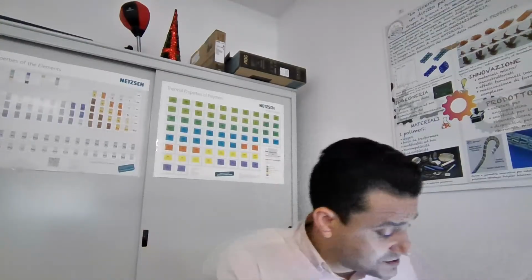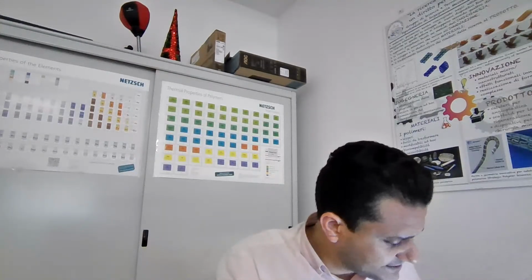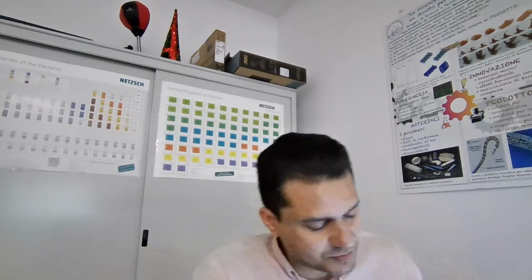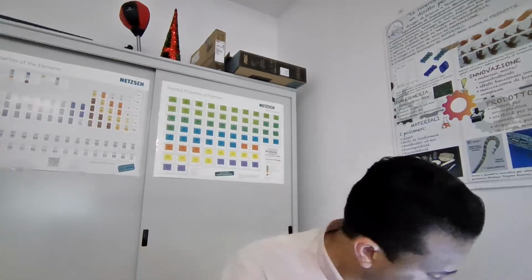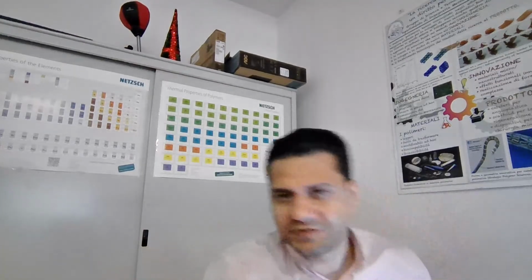I will explain. So the author considered two solids in contact at low nominal pressure, so sigma zero equals Fn over A0, which is the nominal pressure, where the contact area is proportional to the load.